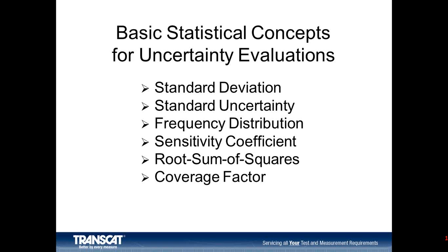So from these steps, we can identify an uncertainty influence for each parameter. Then we combine these different parameters together, generally using root sum of squares. There are some constraints about that we'll talk about later. And then the final step in this ISO recommended method is to expand that from the approximate 65% level back up to about 95%, typically by multiplying by 2, often referred to as K factor of 2, K equals 2, or coverage factor is equal to 2.